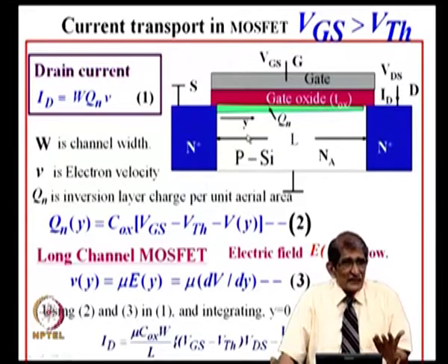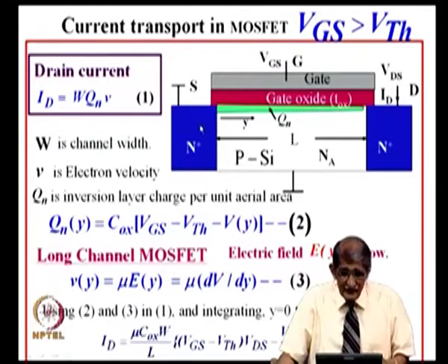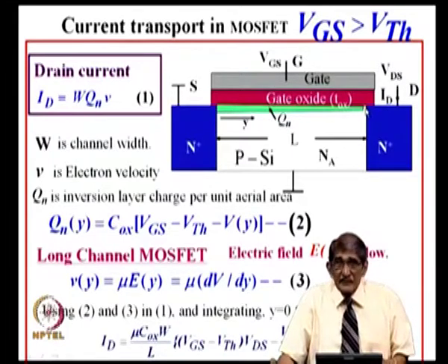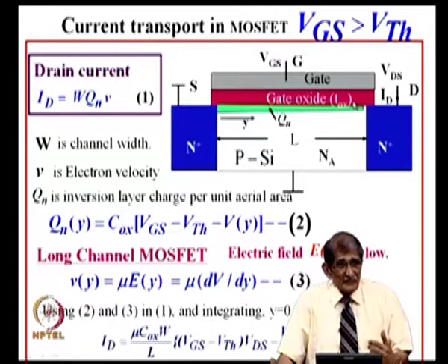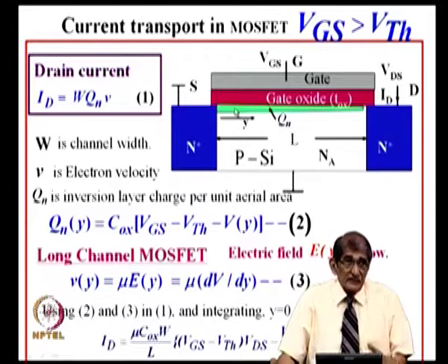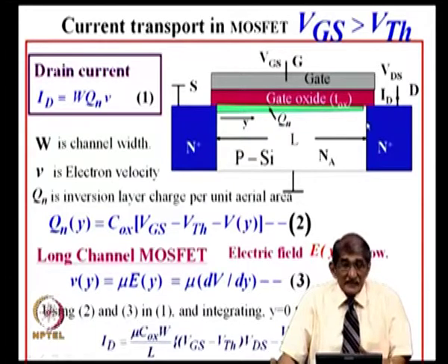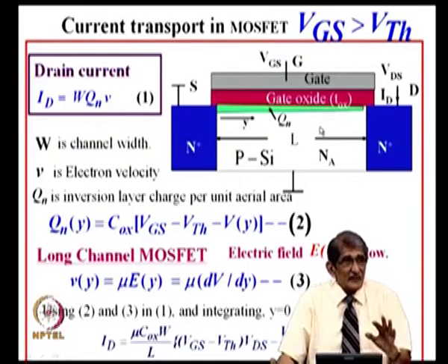It is almost like a bipolar transistor. The difference is, here the electrons are injected and they flow by drift, and they are collected by the collector; here we call it the drain. In the bipolar transistor, there is no field in this region; electrons are injected from the N plus region to the P region, there is no inversion layer because there is no gate. They move through this region by diffusion and are collected here. That is the difference, the transport mechanism.